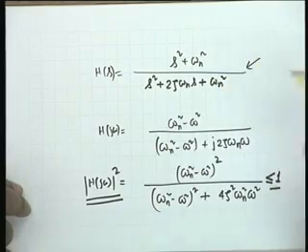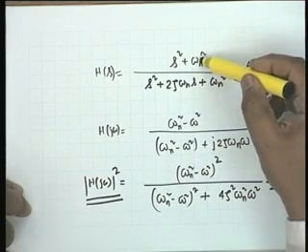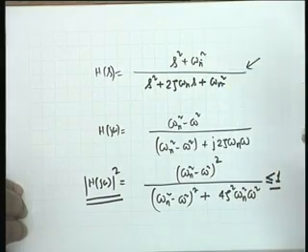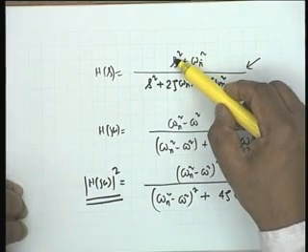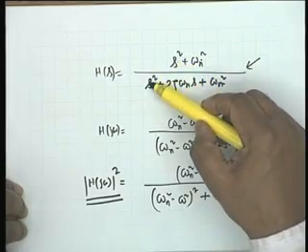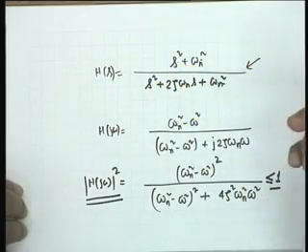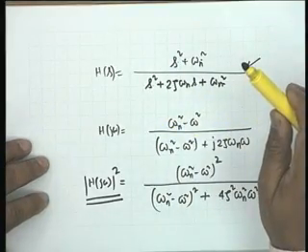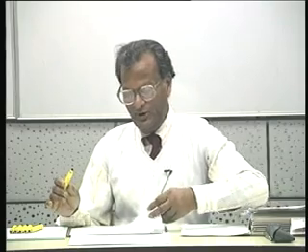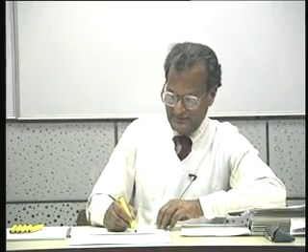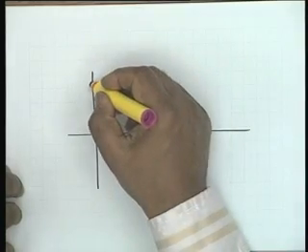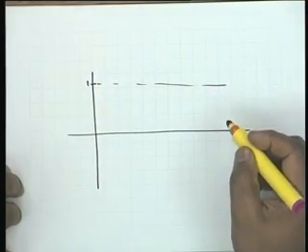Let's find out at s equal to j0, that is at 0 frequency. Omega n squared by omega n squared, so the magnitude is 1. At infinite frequency, it is this term which dominates, so at infinite frequency also the value is 1. There is no other value in between where it can reach 1. And therefore the magnitude plot must start at 1 and end at 1.